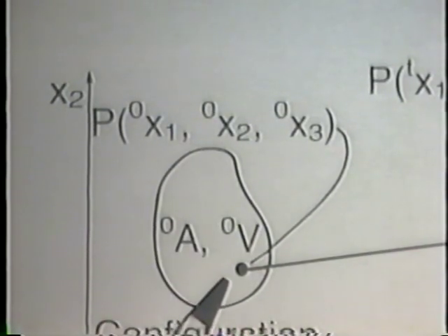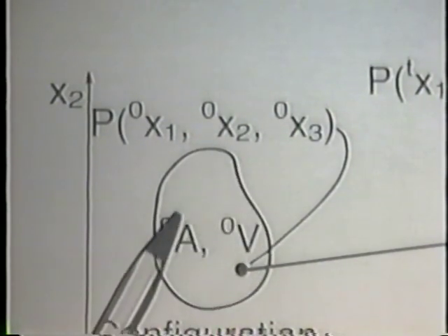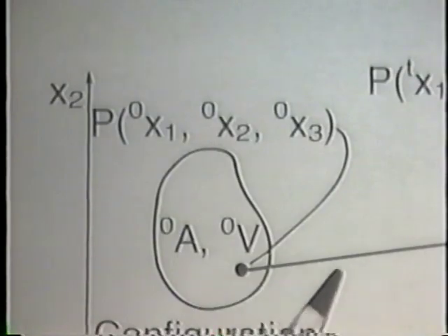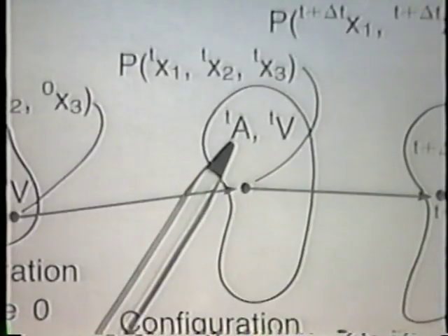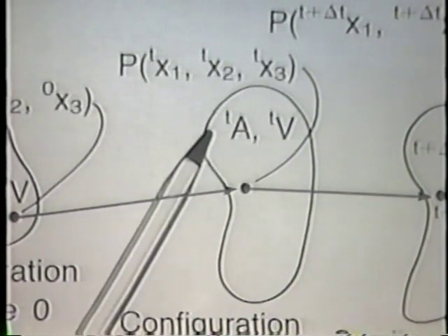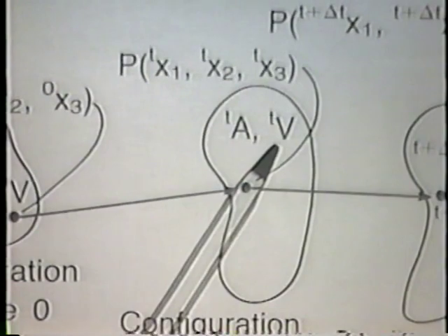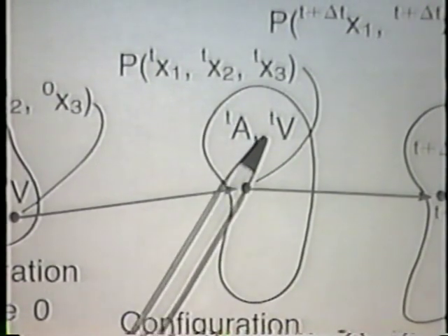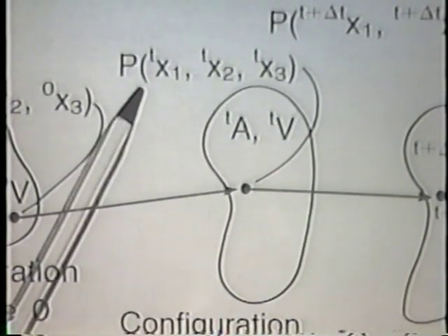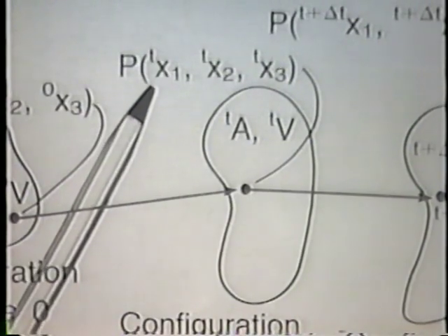This is a particular material particle. This material particle will move with the body from time 0 to time t, as shown on this view graph. Of course, at this particular time now, the surface area of the body has become tA, t now meaning surface area at time t. And the volume of the body is tV. Notice that the coordinates of this material particle now are tx1, tx2, tx3.